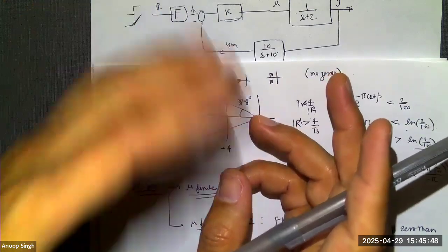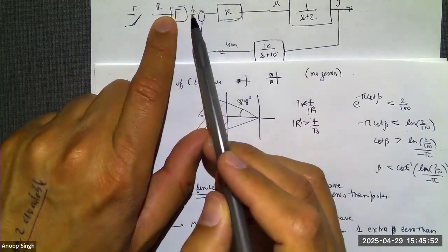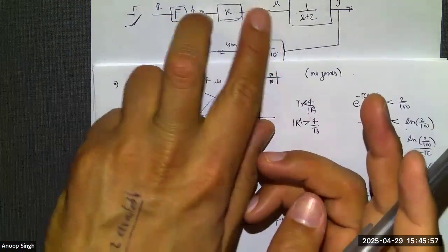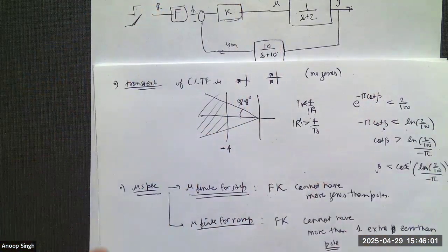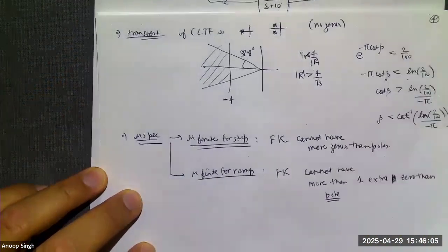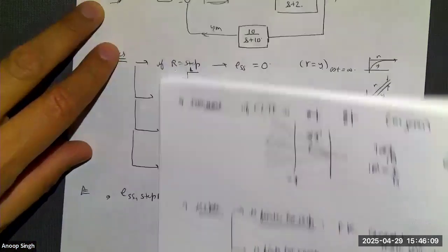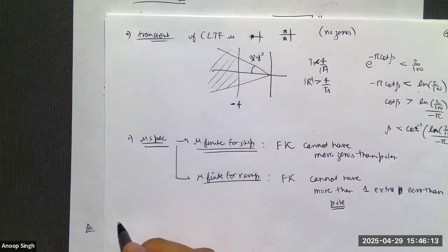But if you are looking for a little bit more fleshed out detail on how the zeros in the controller or pre-filter lead to differentiation in time domain, just convert those transfer functions back into time domain and see. Or refer back to those lectures. But this is kind of the end result. Okay, so I have all the basic ingredients done for all the specifications. Now it's time to try root locus and see what kind of controller will do.